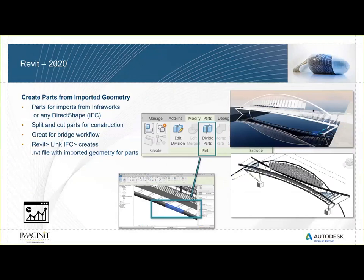Parts are kind of near and dear to my heart. I like the parts tool, and in this case what they've added is the functionality to create parts based upon direct shape geometry or InfraWorks information. So remember InfraWorks from our earlier conversation, this is an InfraWorks bridge that was brought in, and we're allowed to basically create parts of that. So I can take this image right here. This right here would be a single part, but this right here, we would actually split up and divide with the parts tools. So great functionality for that.